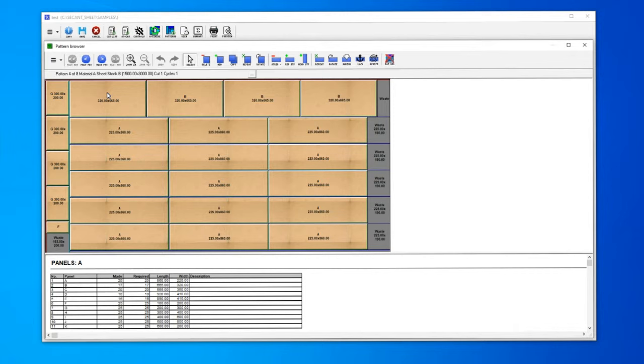Secant will allow you to make any modifications to the patterns which you wish, even if these violate rules such as third phase cutting or indeed overuse the sheet. It will, however, flag any of these errors if they do occur. The printed report will update automatically as you make the modifications to the patterns.